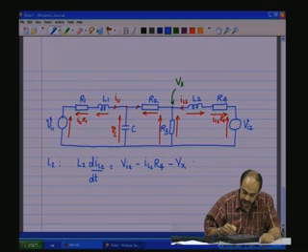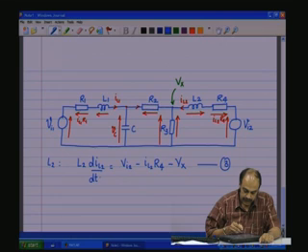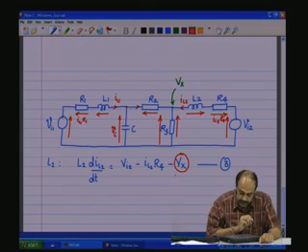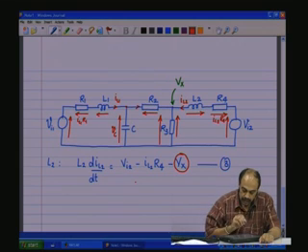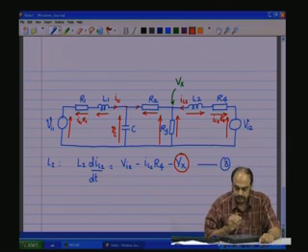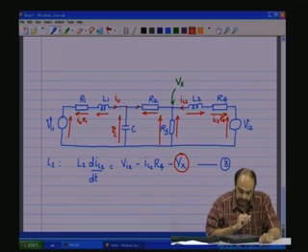And the third equation is this, which is revolving around the dynamic element L2, which is L2 d IL2 by dt is equal to Vi2 minus IL2 R4 minus Vx, and Vx again is the intermediate variable, which is expressed as above. So, which means all three equations are expressed as functions of input variables and state variables only, the intermediate variable being expressible in the form of state variables.